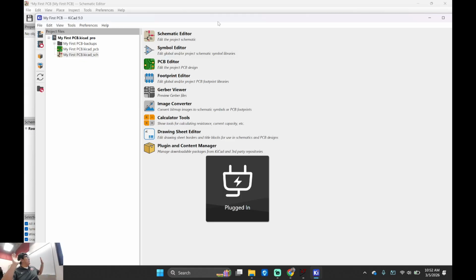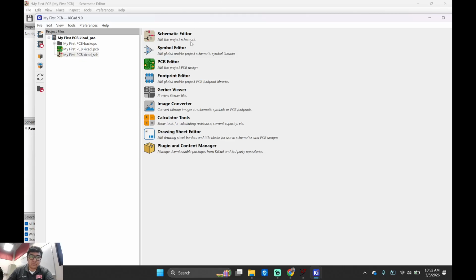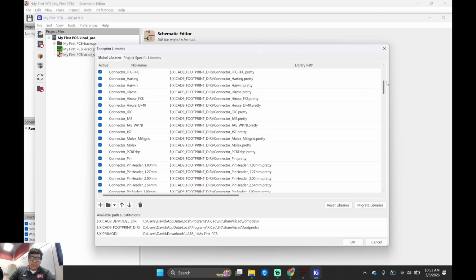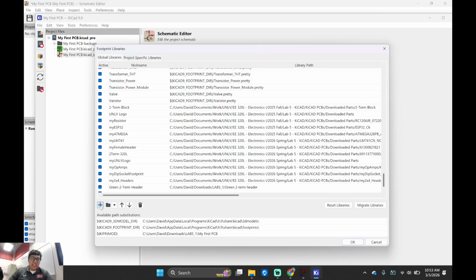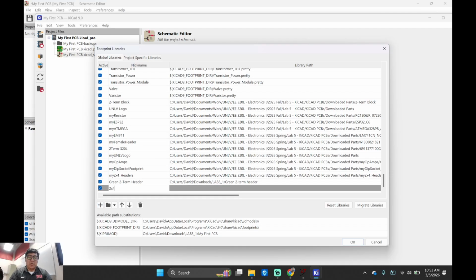See if this doesn't ruin the video. Okay, we're good. I just did the symbol, right? Let's do the footprint. Footprint properties. I'm going to rename it. I'm going to do a 2x4 header. Should I just call it head?